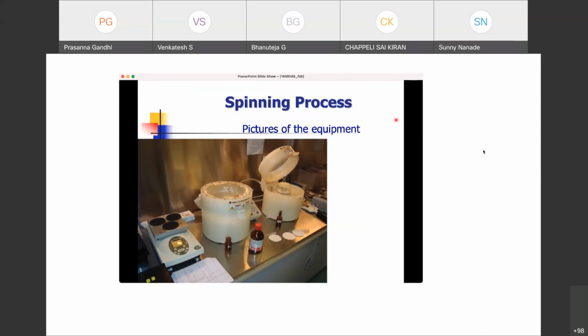When you expose light through a small window, the light will flare up as the window size decreases, and that is the effect. To reduce its effect on the wafer, we need to get the wafer very close to the surface of the mask, so that when the wafer and mask are very close, you don't have much room for that flaring to happen.